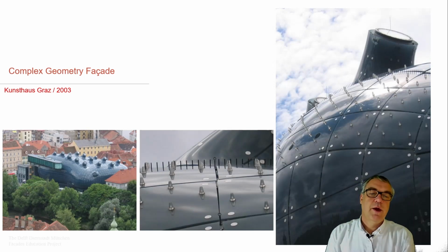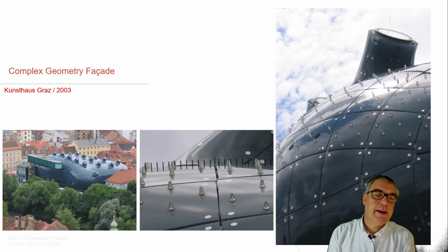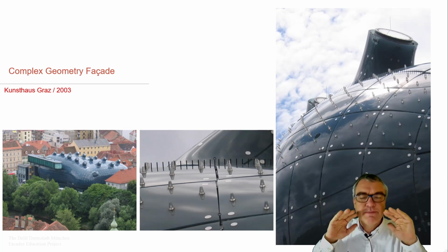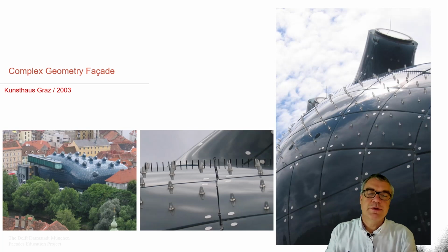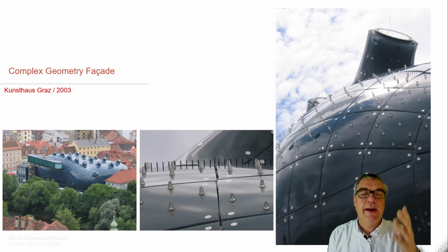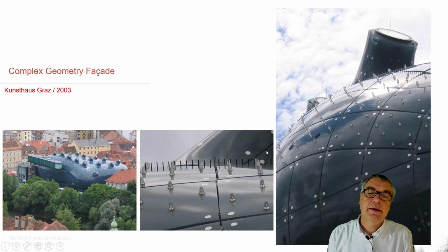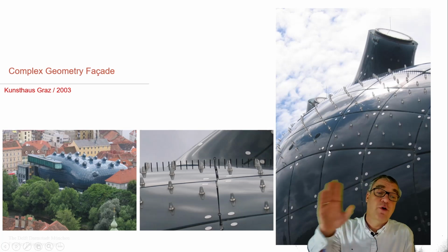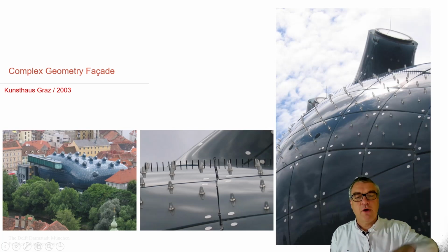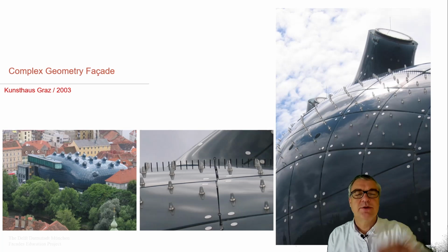And now this one, where we see super advanced polycarbonate plates. So the plates are not straight anymore. They were expected to be freeform curved. This was at that time not possible in that quality in glass, so they ended up with polycarbonate plates, and you see the polycarbonate plate being freeformed. Polycarbonate is simpler to form. Obviously, you need to deal with fire, which is a certain aspect, so the outside of this structure needs to be sprinklered. These nozzles are made to prevent snow falling down if there's a snow situation, so that it sticks to the system.